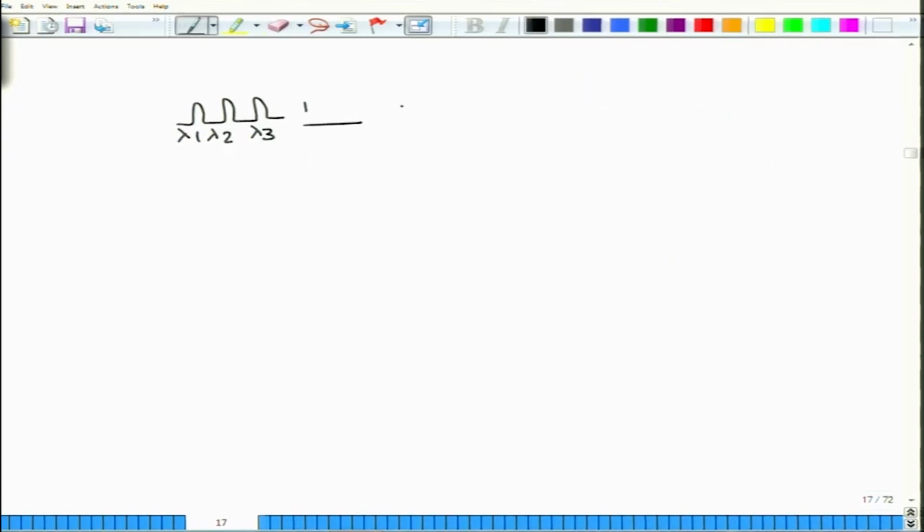Circulator is fine. So the way to put that one would be slightly different. So I will actually have a circulator here, with 1, 2 and 3 ports. Now here I will have a filter, but I don't have any filter. I have a very specific filter which I will call a fiber Bragg grating. This is a grating which is created out of an optical fiber itself, and this specific grating is called a fiber Bragg grating, and this will act as a filter or a selective component.